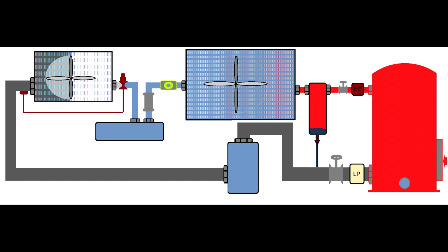This is again the same situation, but the system is not undercharged this time. You start losing refrigerant. In this case, the low pressure switch will start to short cycle the compressor. If you have an electronic device that counts how many times the LP will cut the compressor in 1 hour or 10 minutes, you're safe, because after a while it will cut it out and it will not restart it.